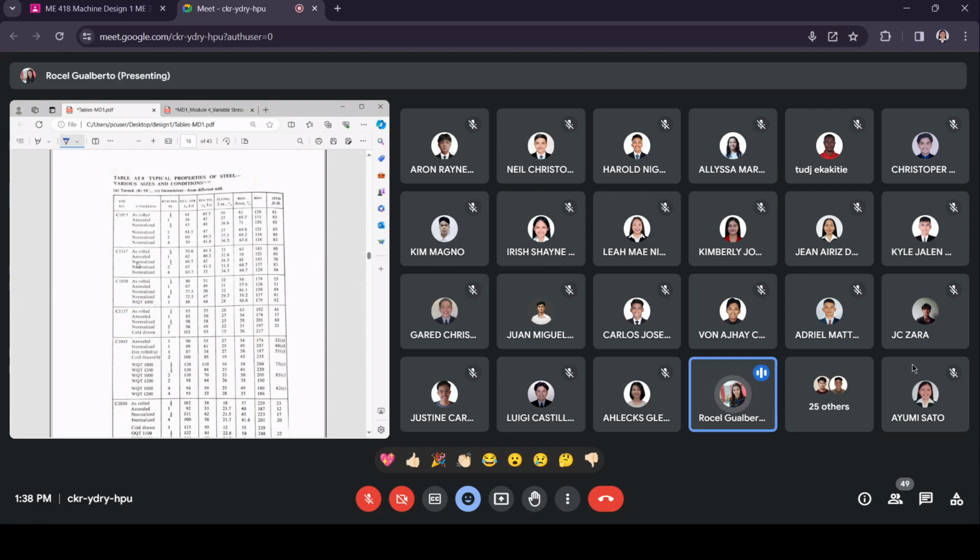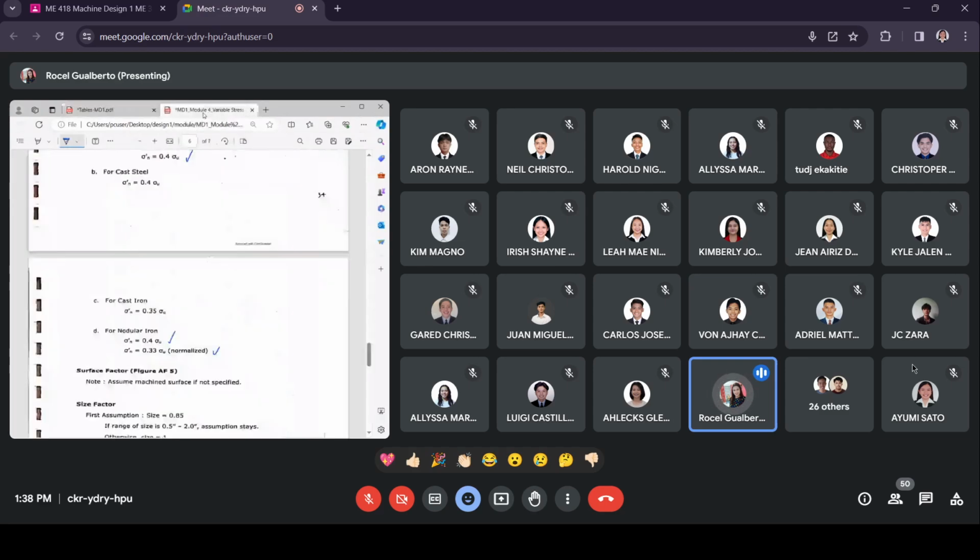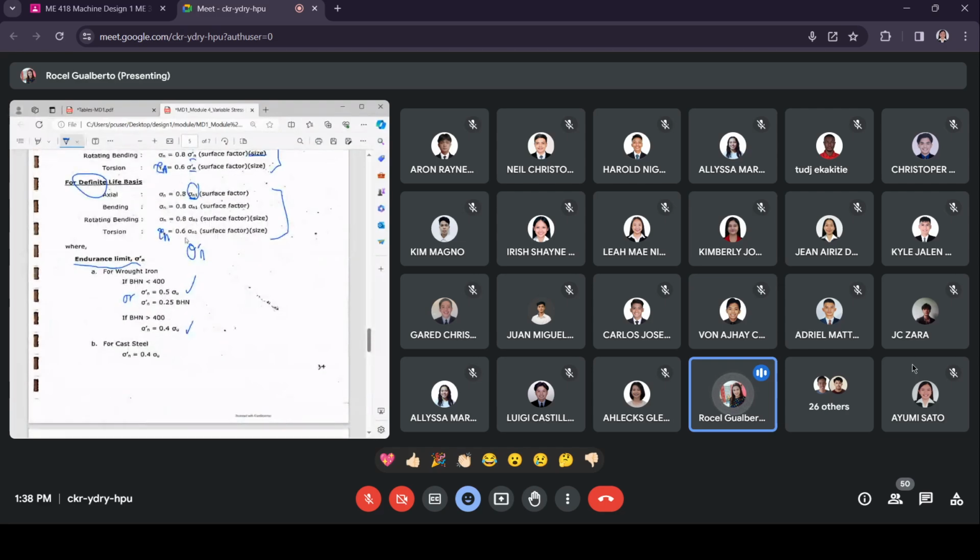So what you need to do is simply to see the BHN value. Is BHN less than 400 or is BHN greater than 400? BHN again refers to the Brinell hardness number. That defines the strength and hardenability of your material. So if you have their BHN value less than 400, then how do you obtain sigma prime n? You use 0.5 of sigma u. If it's greater than 400, you use 0.4 of sigma u.